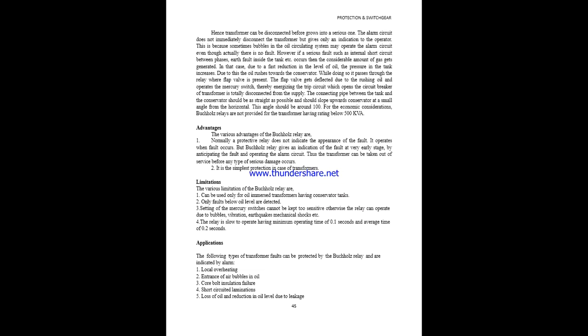There are certain limitations: it can be used only for oil immersed transformers, not for others, and only faults below the oil level are detected. The relay is a slow one, operating for a minimum operating time of 0.1 seconds and an average time of 0.2 seconds, but it has many more applications.